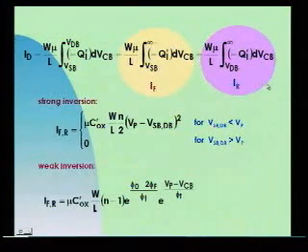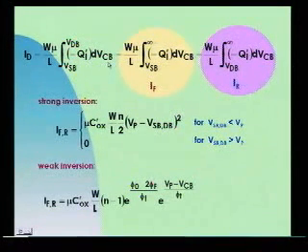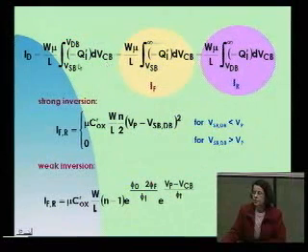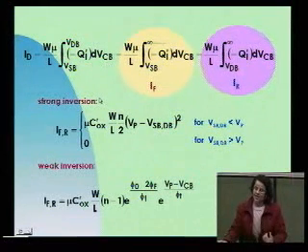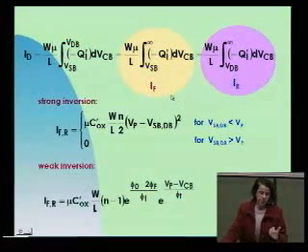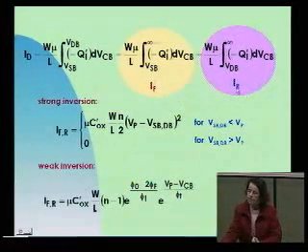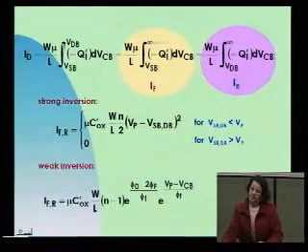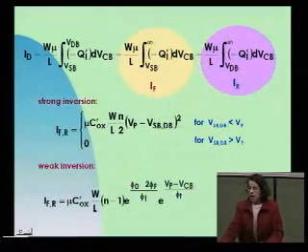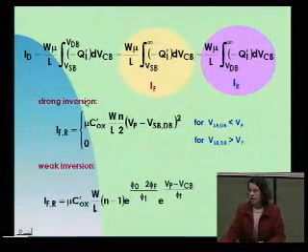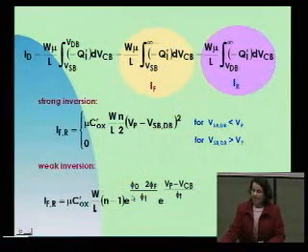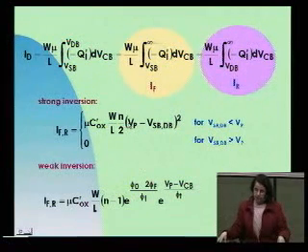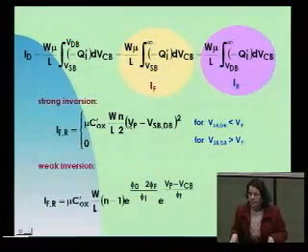Now, I have to integrate these two expressions with respect to the channel voltage, but to have more explicitly the forward saturation and the reverse saturation components, we separate this integral into these two integrals, okay? And then we have these two asymptotical approaches for the drain current.